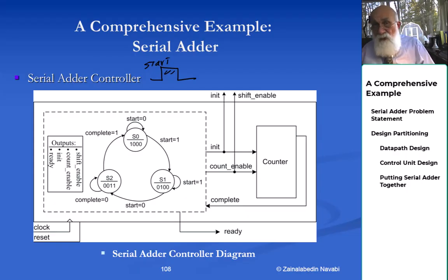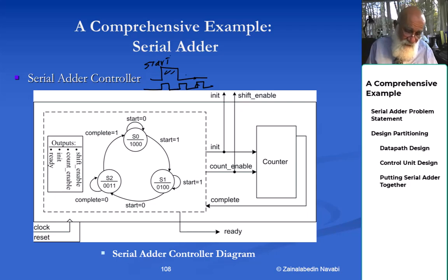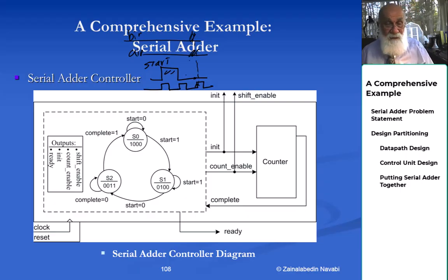It just does the initialization. But then when it becomes 0, then the next clock pulse, let's say this is the clock, starts taking data from A and B. So if this is the start, this is my A, this is my B input, A in, B in. Starting here, my count begins, and I'm picking up data from A and B and adding them together.